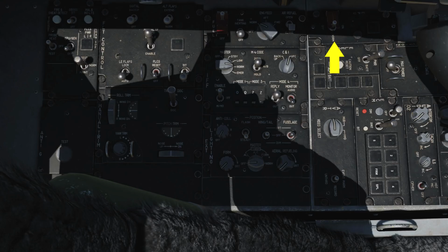At the bottom of the panel is a guarded EPU switch. In the normal position, it operates automatically when the conditions demand, like the loss of hydraulic systems and/or both the main and standby generators. But it can also be manually used in the on position. When the EPU is running and within the proper turbine range, the EPU run light illuminates. The air light illuminates when the EPU is engaged and running on air and not hydrazine, and the hydrazine light is lit when the hydrazine is used to power the turbine.